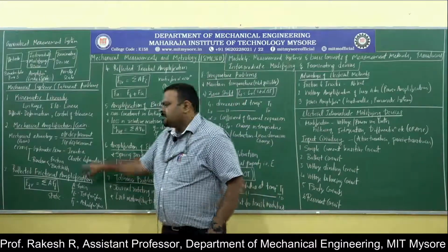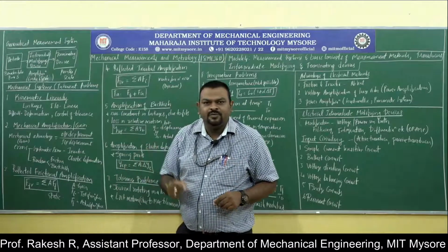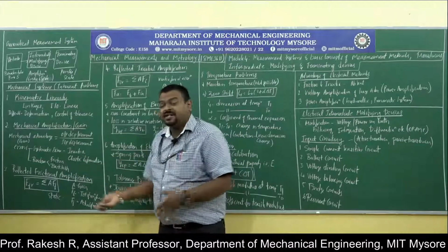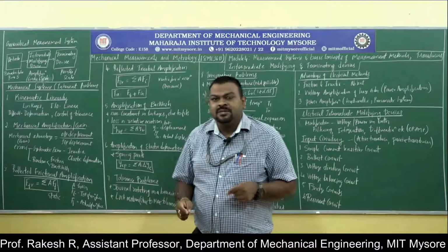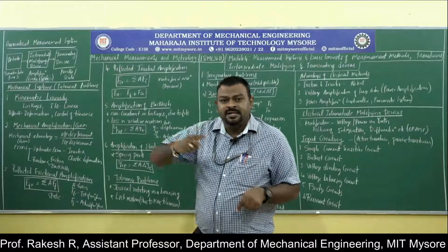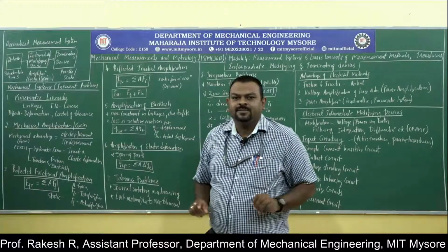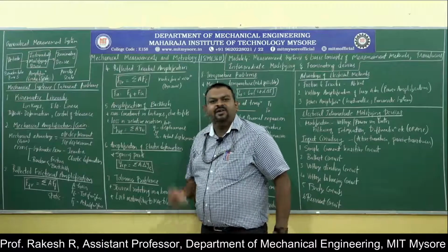Sometimes there will be no reading. The pointer will not move because of friction, because of backlash, because of any systematic error. Sometimes the pointer will move. Sometimes it takes some time to move. So why does this happen? Because of error. So these things will be affecting mechanical amplification or gain.